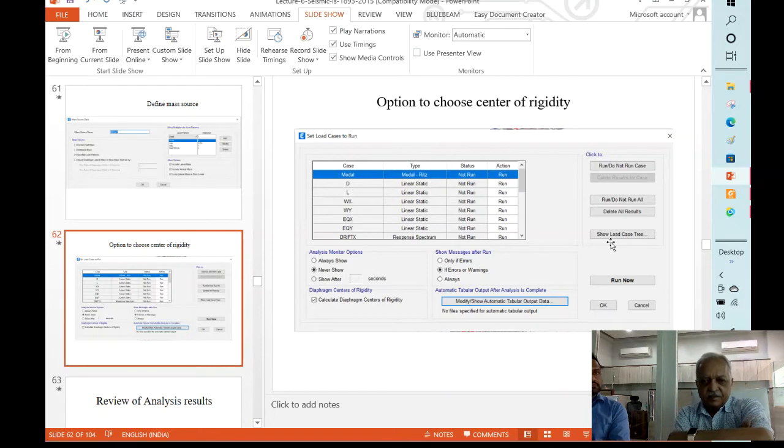So all these constitute our normal data. Then we have to consider, later on, when you consider more complex buildings, you come to a conclusion that the building has got its first mode in torsion. Sometimes you come across such a situation, and the code has given, or particularly tall buildings are scrutinized by high-rise committees, so they insist that your first 2 modes should not be in torsion mode. So to understand what constitutes torsional mode, you need 2 points. One is where is the mass center and where is the stiffness center.